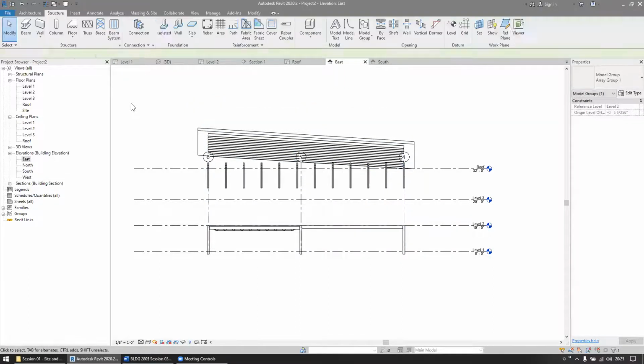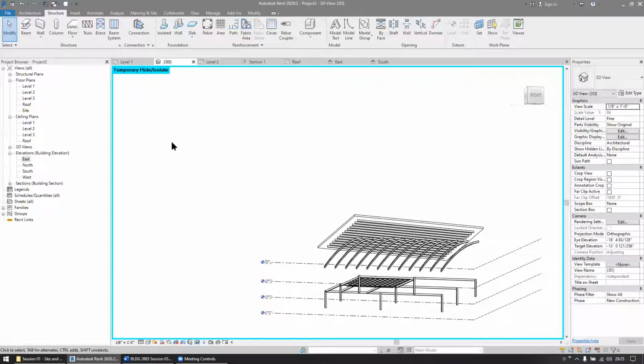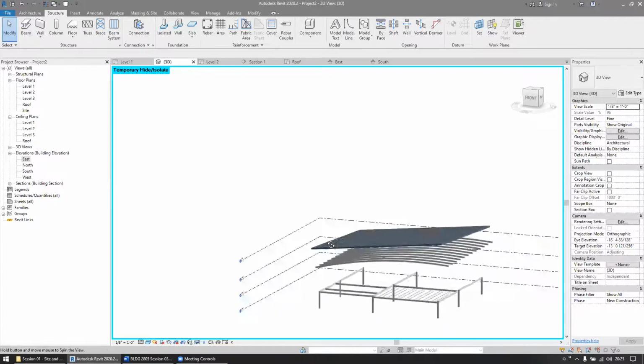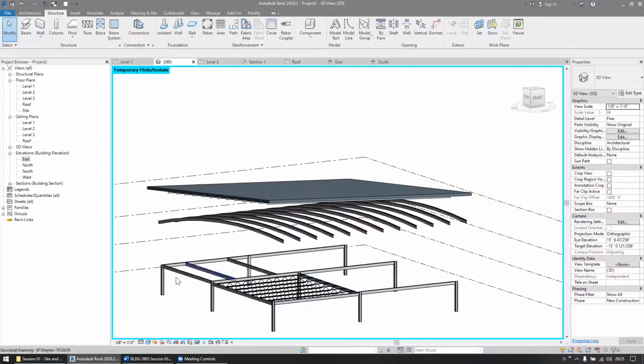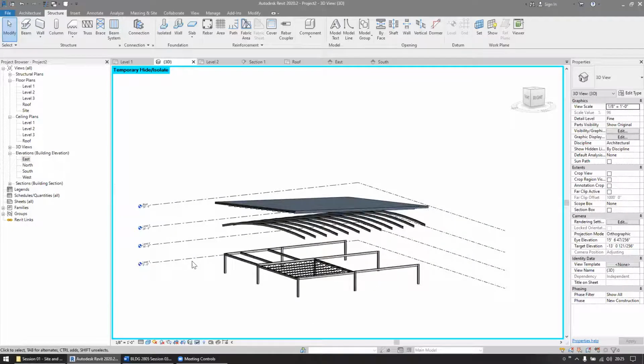So I don't know exactly what spacing that is, but when we look in 3D, you folks can see that, having placed that one beam on grid 6, I can just copy the rest of the beams sideways, like you see in our notes about halfway down page 4. Okay, any questions so far?